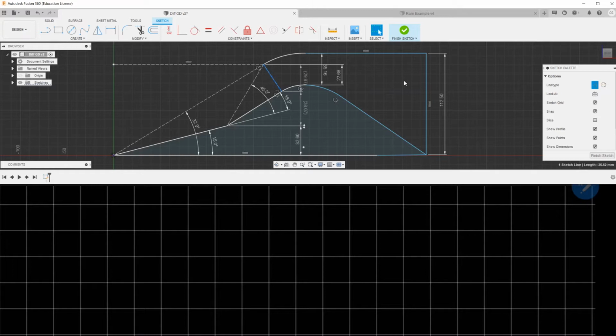For us, it means that flow can transform to any shape, right? To any cross-section we want. What happens when we constrain more here, you understood, I hope, that we'll just choke the flow. If it's open too much, flow can become supersonic, or can stay again subsonic.